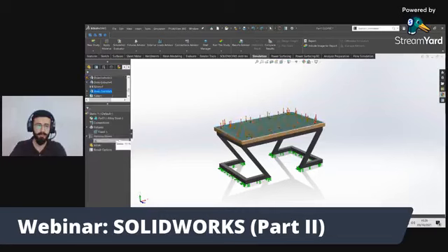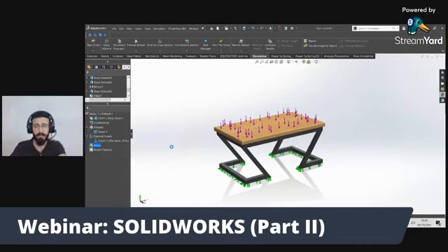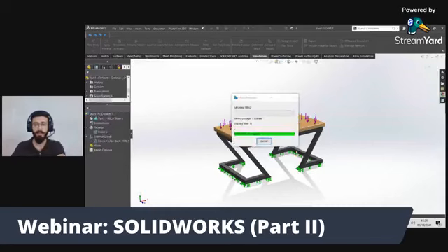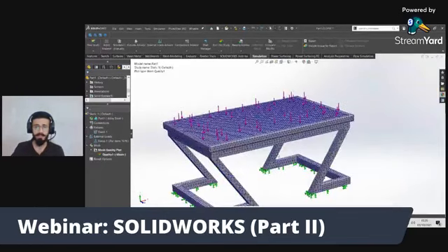Then there is the mesh manager. Now I will apply mesh, create mesh. What is the use of mesh? It gives data to SolidWorks Simulation about how compact this is made. There are some steels, some wood which is hollow from inside. If you increase the mesh quality, it shows the simulator that this object is a compact, solid object. So I will increase the mesh quality to high. Okay, done. Now the mesh is being created. All done. See, this is the mesh. This is of excellent quality.